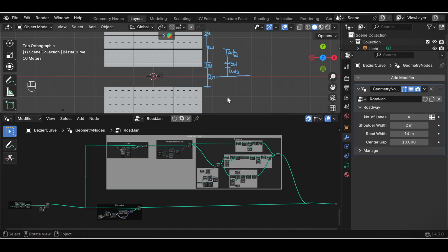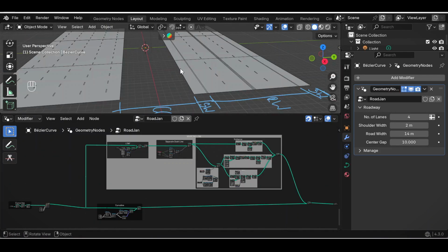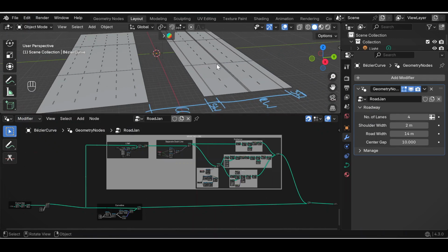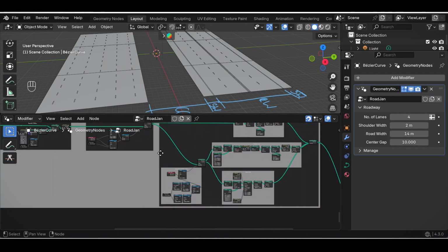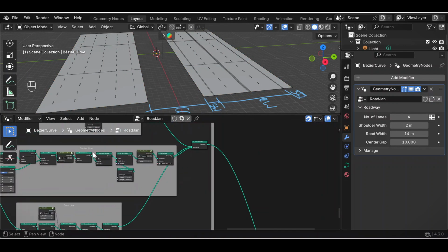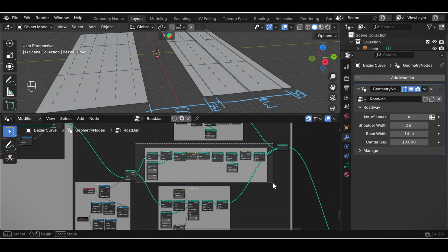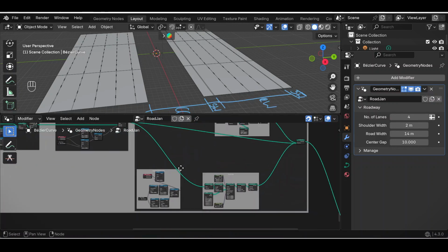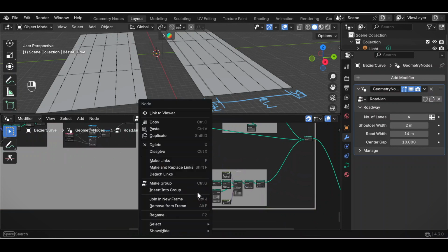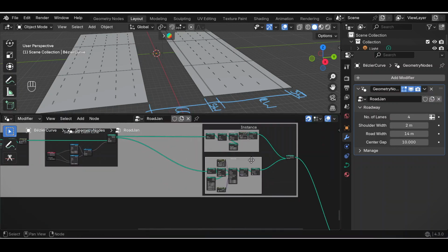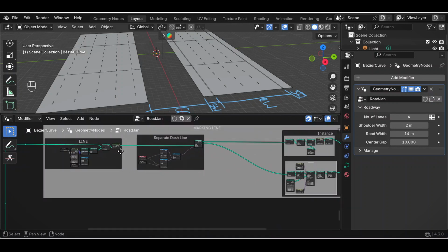We encountered an issue with the lane markings. While they are correct on one road, they are misaligned on the other. Additionally, this route has a centerline marking, which is unnecessary for a dual carriageway. The first step is to remove this unnecessary marking. Once that is done, we need to fix the lane markings on the other road.